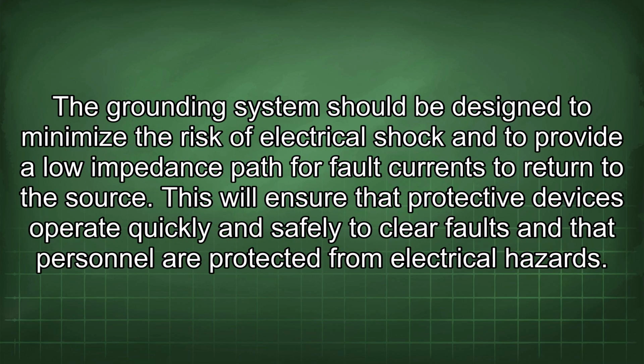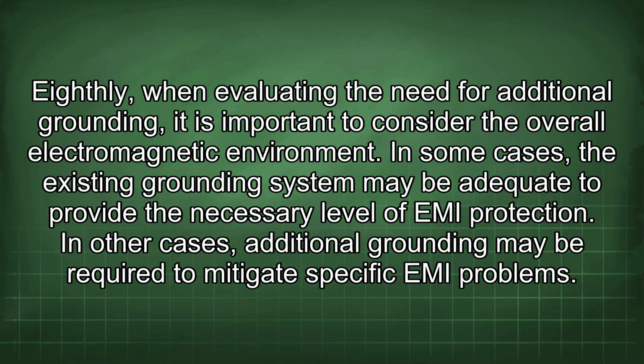The grounding system should be designed to minimize the risk of electrical shock and to provide a low impedance path for fault currents to return to the source. This will ensure that protective devices operate quickly and safely to clear faults and that personnel are protected from electrical hazards.